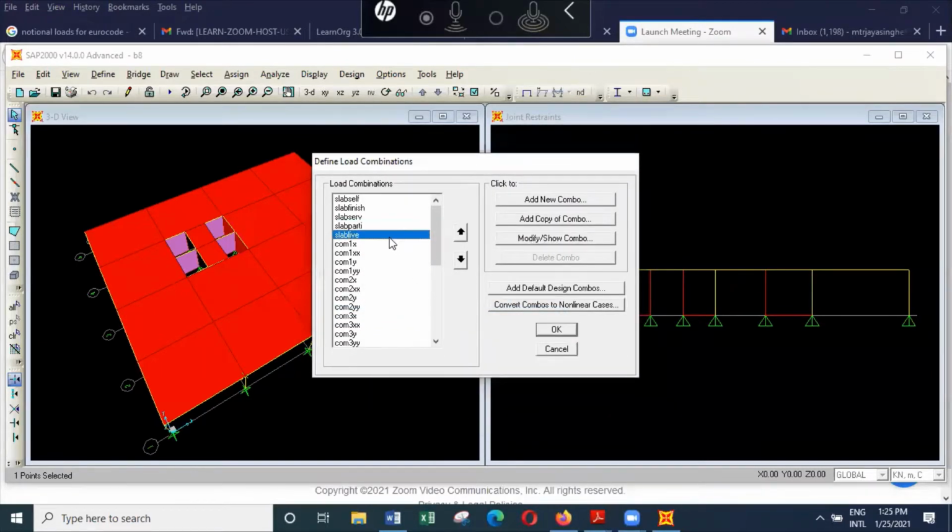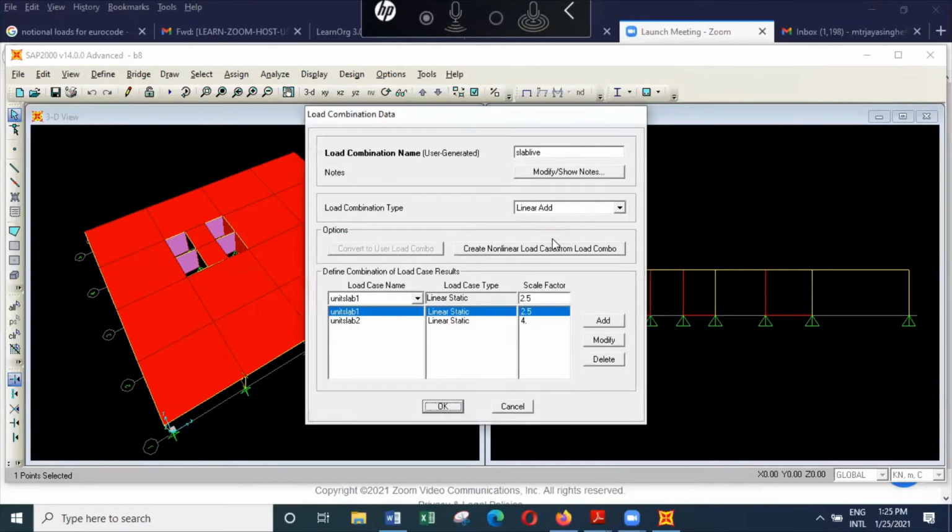And then we also have to look at the live loads. I have considered a different live load for this area, that is 4. And for all the other areas, I have considered the typical office floor live load, which is about 2.5 kilonewtons per meter squared. So with those, we can actually convert the load on slabs to the corresponding loads on beams.